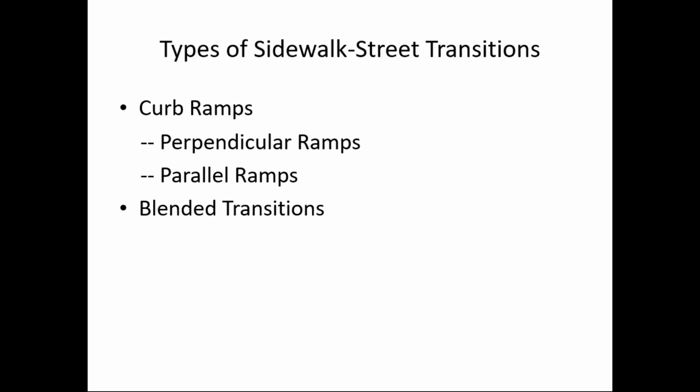And the answer to that question about PROWAG is it depends. It's correct that PROWAG has not been signed into law, whereas ADAAG has. So ADAAG is law. But there are some state and local agencies around the country that have adopted PROWAG. So in those entities, PROWAG is the criteria we need to follow. And also, as I think I mentioned earlier, DOJ and the courts, through their rulings, are telling us that they consider PROWAG, if not law, the best available guidance to provide accessibility in the public right-of-way.